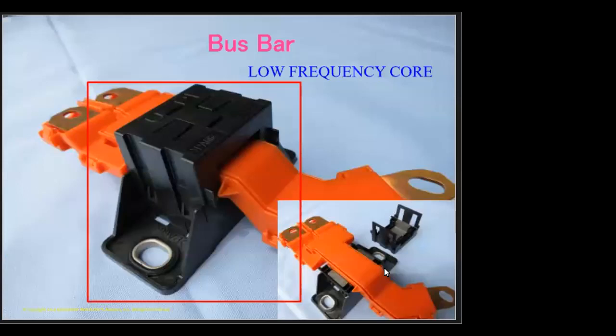This is a bus bar for a hybrid vehicle that connected the battery pack to the inverter. There were some low frequency noise issues during the recharge phase. So a custom low frequency ferrite was made to fit the bar and the plastic enclosure to hold everything together. This allowed for the noise to be filtered out and keep the ferrite from moving and making any noise due to vibration.